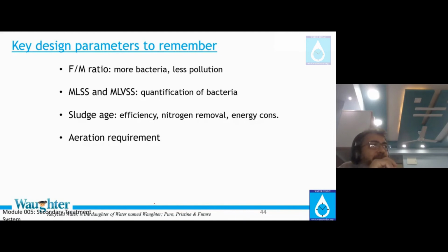So in actual operation, can I go to a customer and say, sir, you have given me a 100 KLD plant to design a sewage treatment plant? Please remember my words, 100 KLD plant. You also said COD is 350. And the same customer says, okay, now my flow rate is only 40 KLD and my COD is also 200. Why the hell your plant is not working? The answer is your plant will not work because you don't have food. As simple as that. So biological wastewater treatment plants are not a mathematical model.